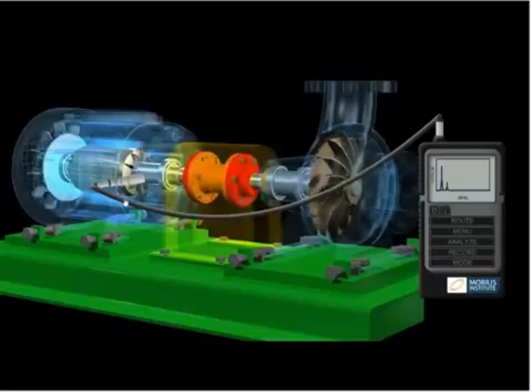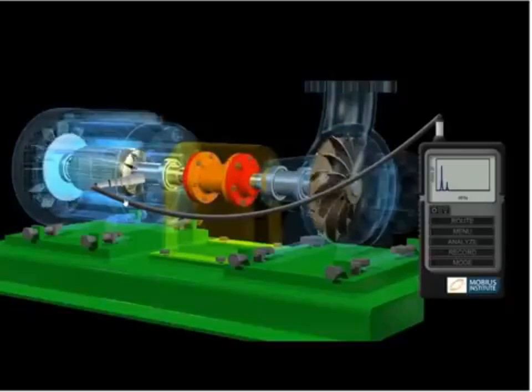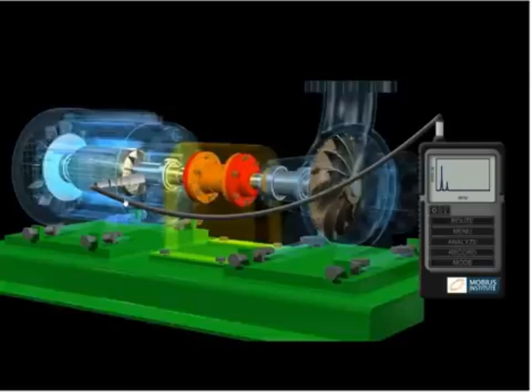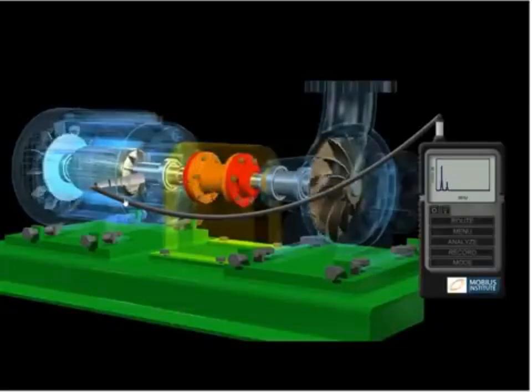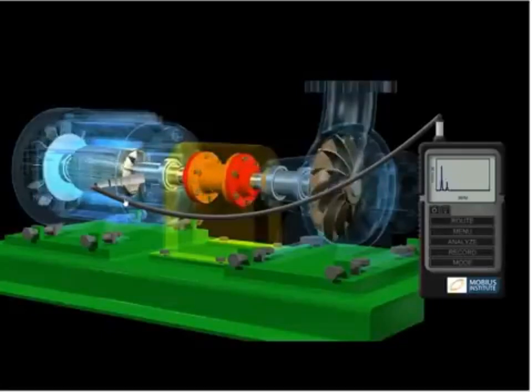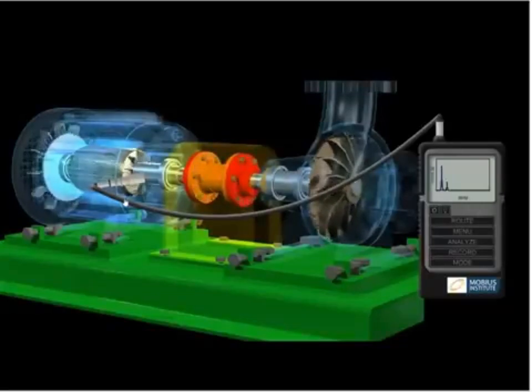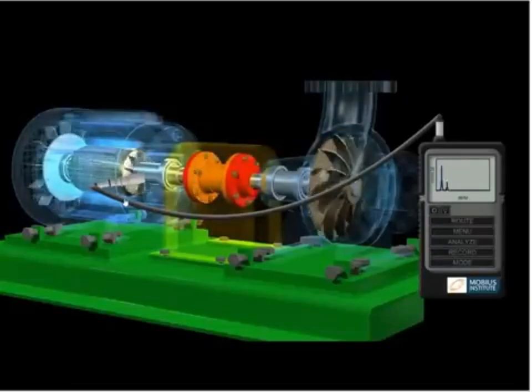Often you can get away with just a horizontal measurement and an axial, but the fact is that with different sorts of machine faults, the vibration changes in different ways in different axes. And so that's why we like to measure on different bearings, ideally on both bearings of the machine component, and in different axes if we possibly can, to get the full picture of the machine vibration.